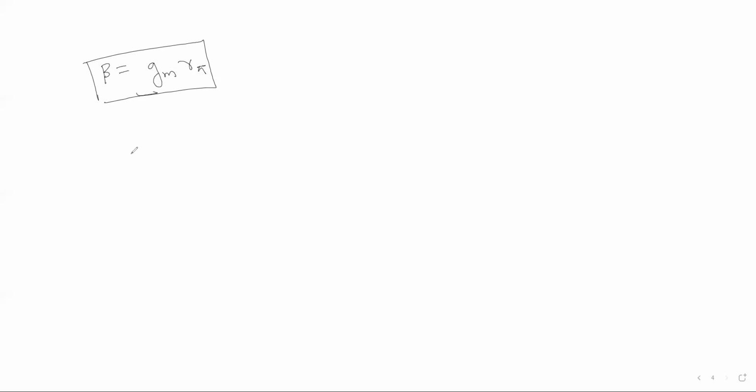So we can replace that gm by this, and we could have that equation: V pi times (1 by Rs, plus 1 by Re, plus (1 plus beta) upon R pi) is equal to minus Vs by Rs.